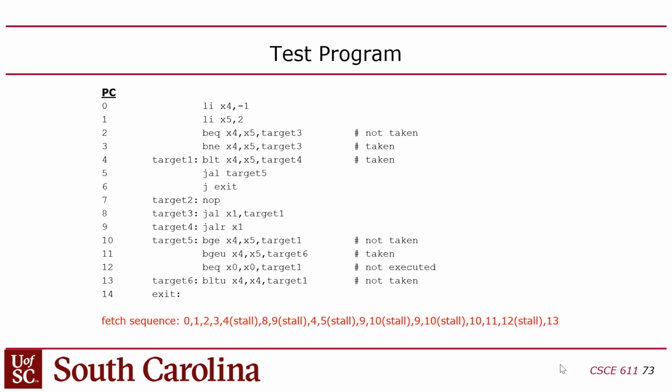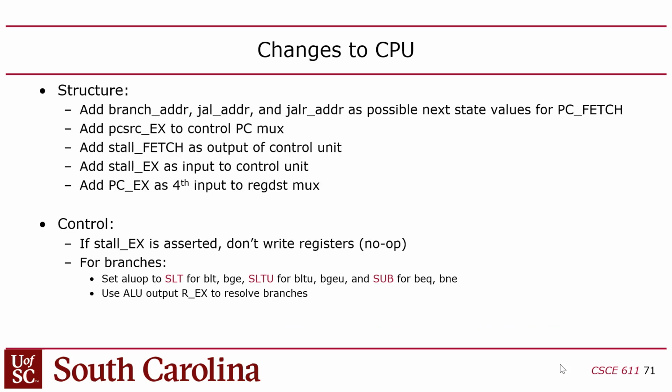When PC5 is the jump and link target 5, is that a format that does not require a register? No, 5 just never got executed because it was a stall. We never actually execute 5. The way you have it coded, there is no register to put the... Oh, yeah, that's a good question. In RISC-V, there is actually a register, but it defaults to register 1.